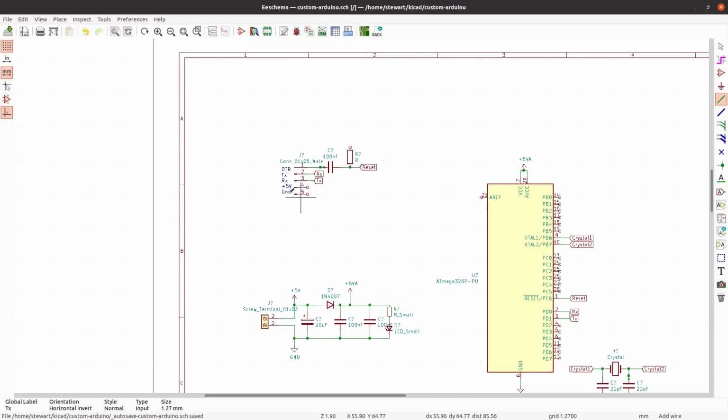Then we've got the 5 volt supply. Start off by just taking the ground, just copy one of the existing ones, and that's going to go there. And the 5 volt supply, I could just wire it straight into the 5 volt, but I'm going to put this through another diode. You shouldn't ever have it powered by two sources, so you should never connect this UART at the same time as there's a power supply down here. But just in case they do, then I want to put a bit of extra protection in.